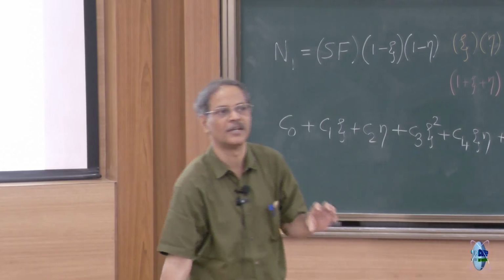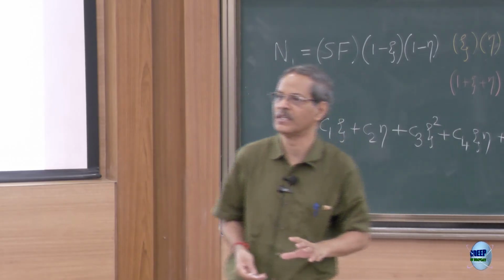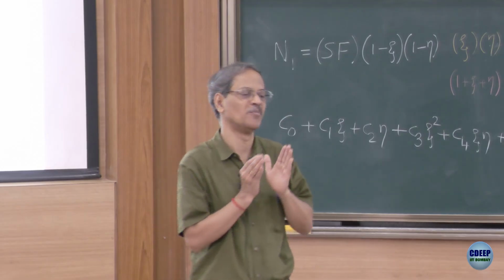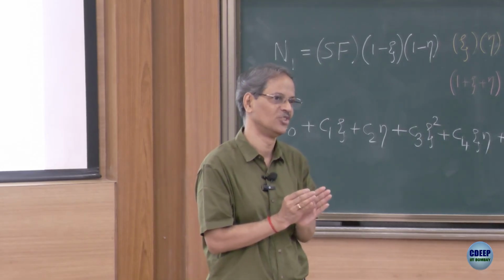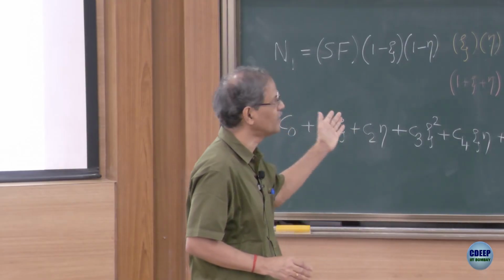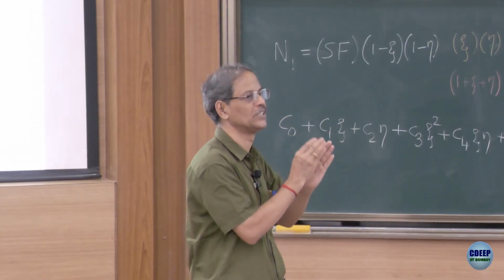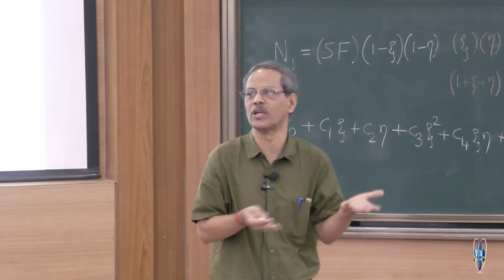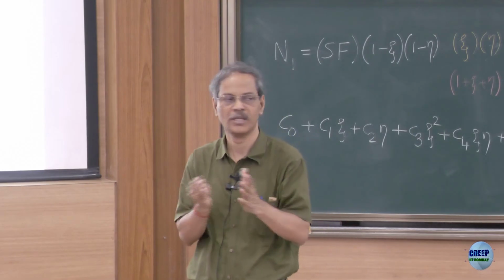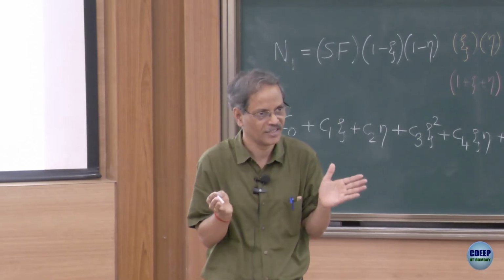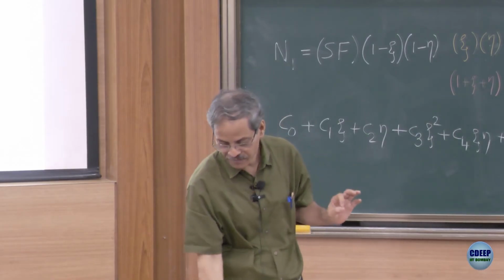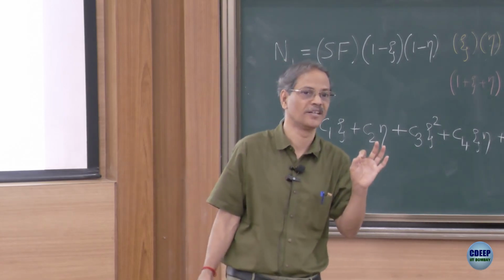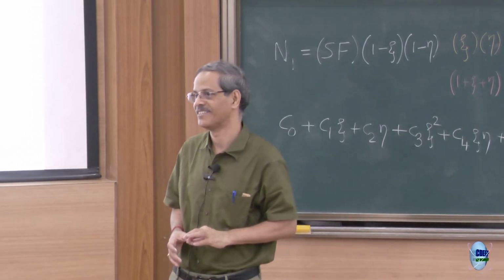The caution or a suggestion when you are doing something like that is to make sure that you are symmetric about the center line. So if you have included zeta squared eta, you also would like to include zeta eta squared. So it is not biased towards any one particular coordinate. That is all that you can try to maintain at least. But we would see that certain additional terms have come in beyond the complete quadratic polynomial.